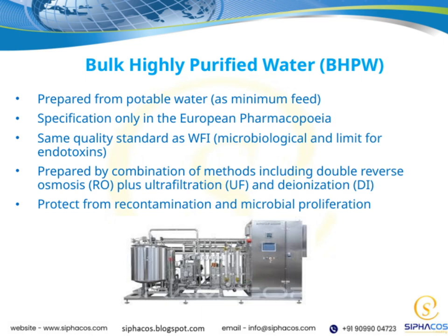and endotoxin limits. This means it's suitable for use in various pharmaceutical processes where sterility and safety are critical. The preparation process involves multiple purification steps, including double reverse osmosis, ultrafiltration, and deionization. These combined methods effectively remove impurities, microorganisms, and endotoxins, ensuring the water's purity.